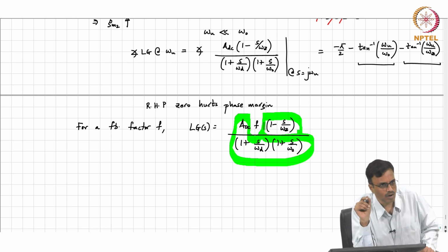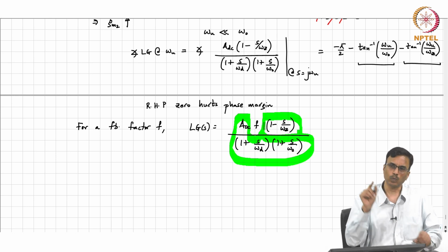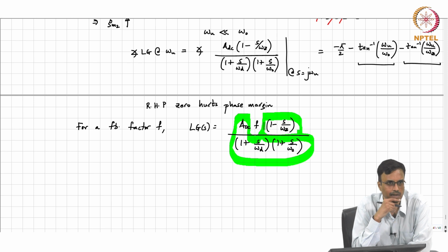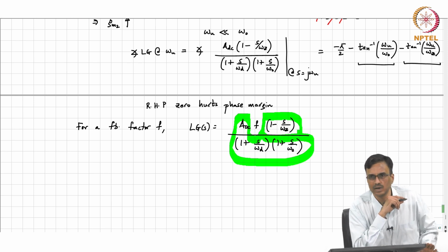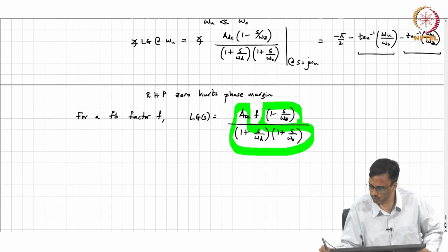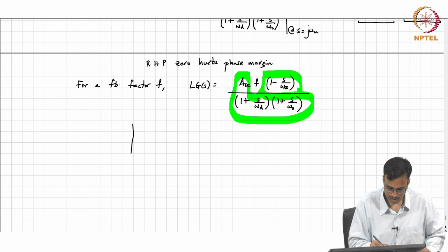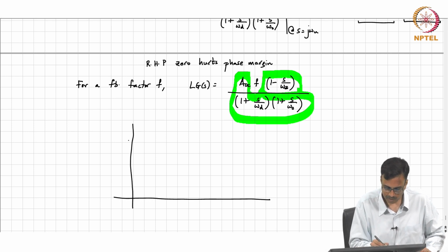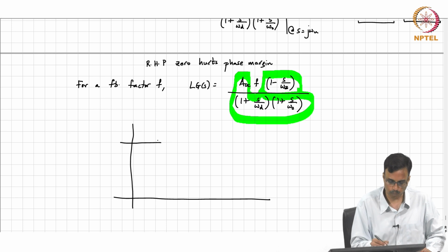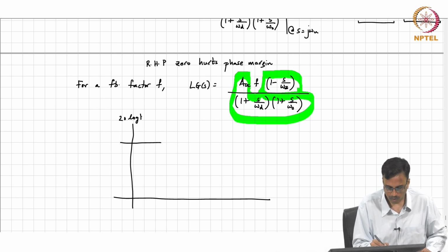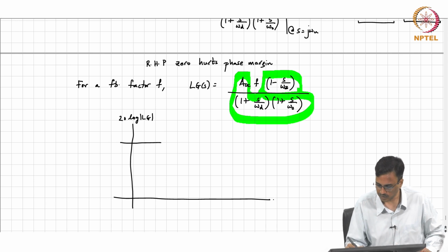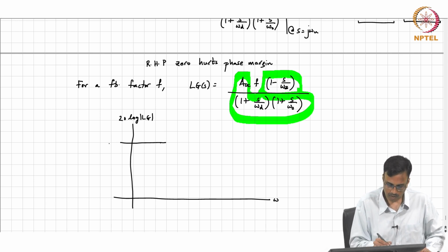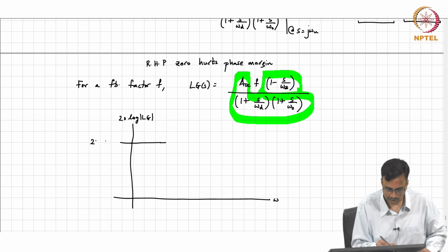So, in this range of f, which is 0 to 1, for what value of f would we be very concerned about stability? So, if f is 0, it is very clear that there is no feedback at all, correct. So, there is nothing to worry about stability, right. Okay. So, for higher values of f, remember that the loop gain function, if you plot it, this is the log magnitude of the loop gain, this is the frequency, then what is this value? Yeah, that is 20 log ADC times f, okay.